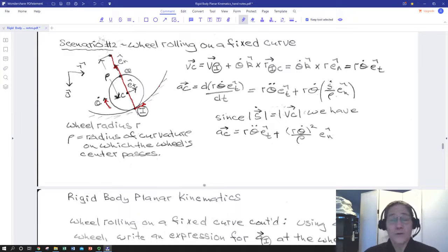Well, we know that point I has zero velocity, so let's use that as our known point. This is really the only one we do know. So we add our angular velocity in the I hat direction, and we cross it into a radius vector from the point we know to the point we're looking at. So it's R I to C, which is going to be in the positive normal direction because we've defined our normal axis as positive.